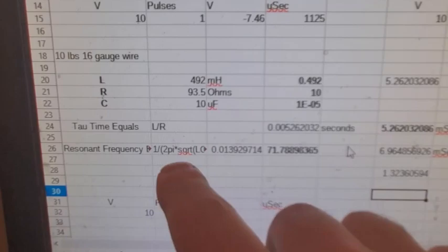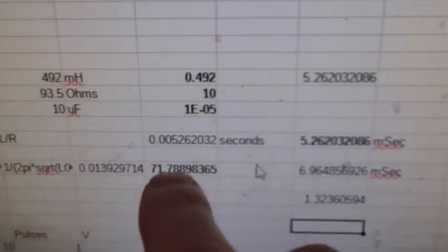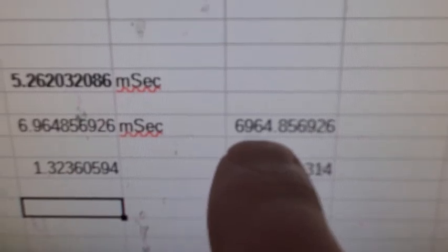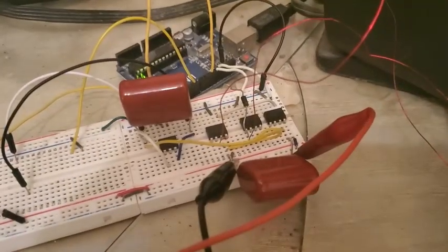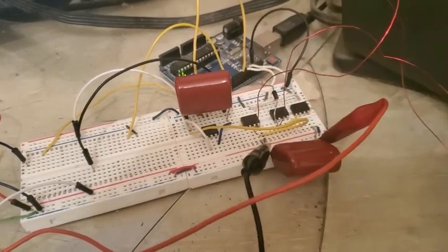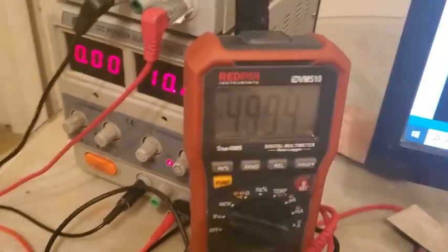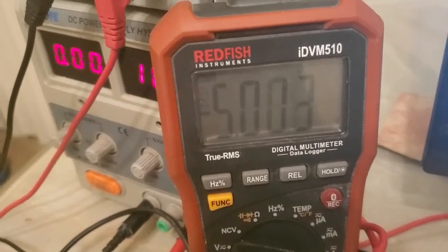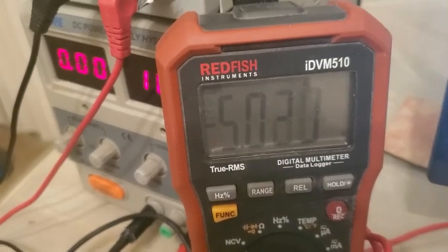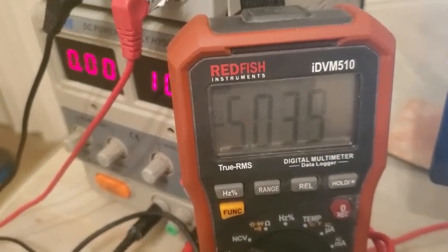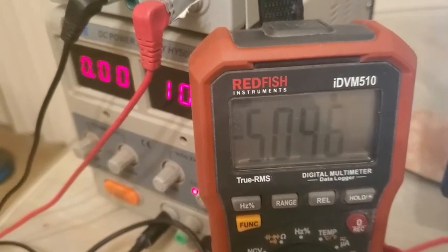So again, this gives us a resonant frequency and gives us the half resonant, where it's going to be most negative. 6,965 microseconds is what we want before we disconnect the LRC tank circuit. I had these two backwards. I was like, what's going on? But this is what we get with this coil. It weighs 3 times as much and has something like 30 times more inductance. And it's only flipping negative to -5 instead of -7.6.